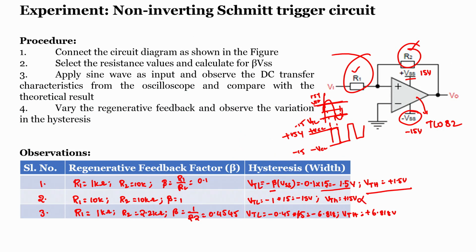But I am not going to do this case experimentally. The reason is that I would require an input voltage greater than 15 volts, but the source cannot provide more than 10 volts as a peak value. So that is why I will not consider this, but if you have a suitable source, you can connect it and visualize, and we can also do the experiment in your labs.